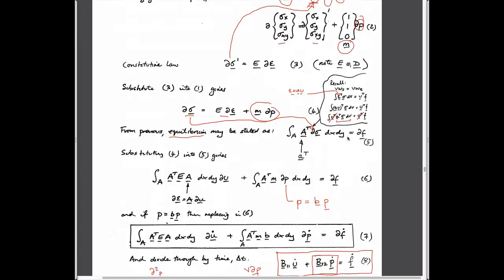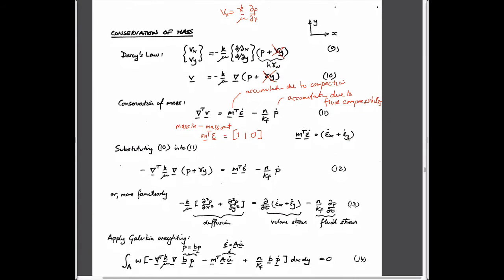And so we take the transpose of that and multiply it by the strains in the x direction, the strains in the y direction, and the shear strains. We have 3 strains. And so shear strains don't make any difference. Shear strains are like taking a pack of cards and deforming them. There's no volume change in shear. There definitely is volume change in normal compaction. And so we end up with those. And so that's exactly what this means. And if we now substitute Darcy's law into this, we end up with this expression. Let's ignore that.